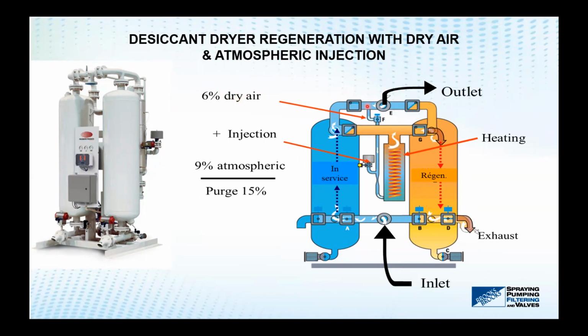we're using the waste energy, and I call it waste energy because you're taking 100 psi air. Air is somewhat of a utility. It has a certain energy associated to it, and it's going through a venturi. By decompressing the 100 psi to 0 psi, it creates a suction and increases the flow rate. And then that flow basically goes across a heater and regenerates the desiccant bed. So I would call this sort of like a hybrid. It takes a bit of the design aspect of a heatless dryer and a bit of the design of a heat reactivated dryer to do the regeneration of the desiccant bed.